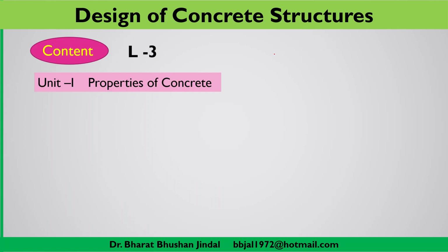First one was when the loading was for a small duration of time, that happens in the concrete testing in laboratory. And then we have discussed how the stress strain graph will vary when the loading is a consistent loading and for a long duration of time.